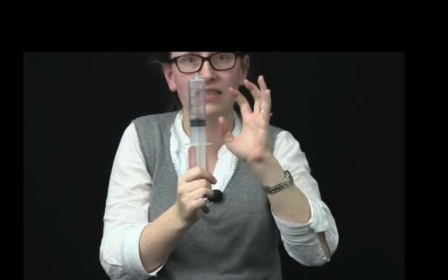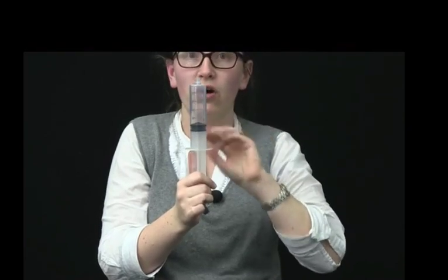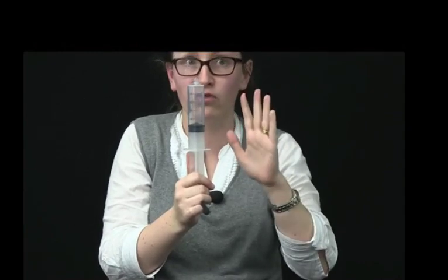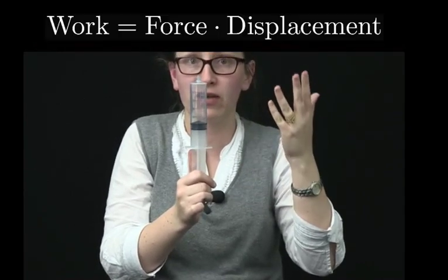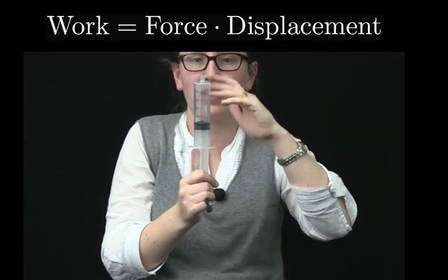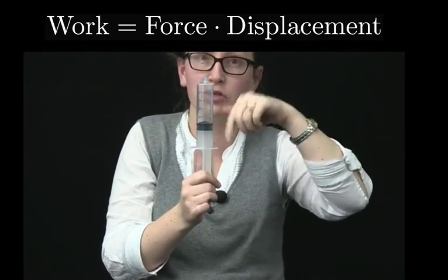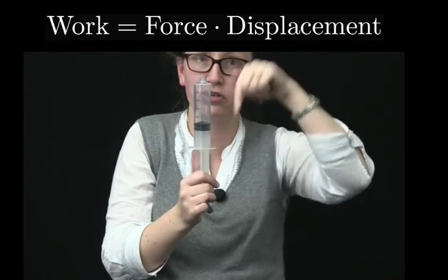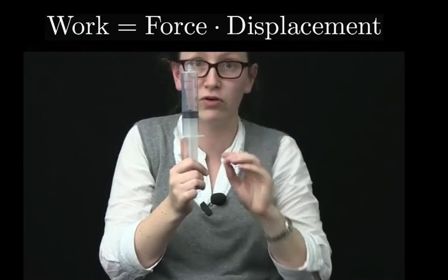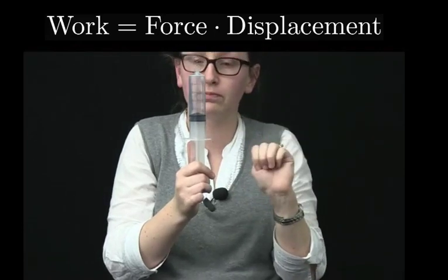This is the most important step in the process, as this is when the fuel is actually doing work on this piston, and so this is when the car actually gets the energy out of the fuel. So work is a way of transferring energy, and it is equal to the force times the distance. So the gas molecules in here apply a force on the syringe, and the syringe moves downwards. The force applied by the gas molecules is also downwards, and so we have positive work done. We are getting energy from the fuel. So the actual car itself is then gaining energy from that fuel.